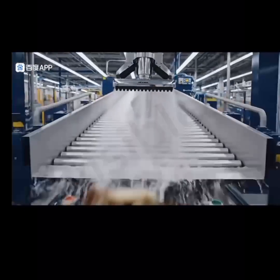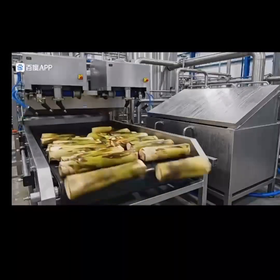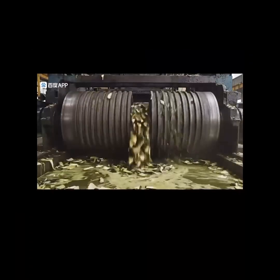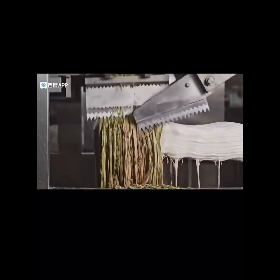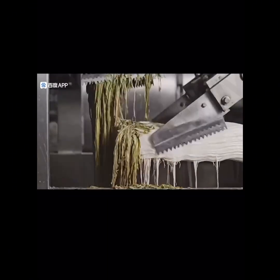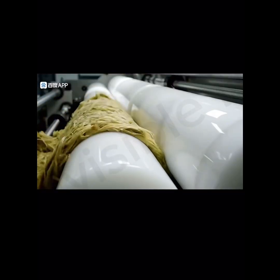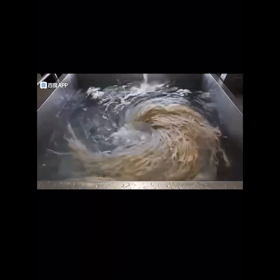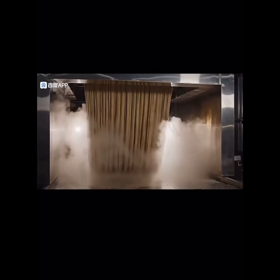Now, we are entering the factory. This is where it gets even more exciting. The first thing that happens inside the processing facility is preparation. The pseudostems are trimmed and split lengthwise. Each stem contains multiple layers. The outer layers are tougher and contain more non-fibrous material. These are separated from the inner layers, which contain higher quality fibers. This separation can be done manually in small facilities or mechanically in large plants.